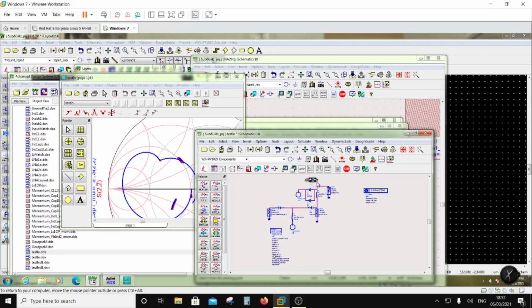So what I am proposing to do is insert a resistance here for decoupling. Resistance can be inserted in the gate bias because the gate doesn't draw any current, right? So that decoupling would be, let's say, 1K. No matter what the internal impedance of this DC supply is, 1K would be so high that it won't matter.